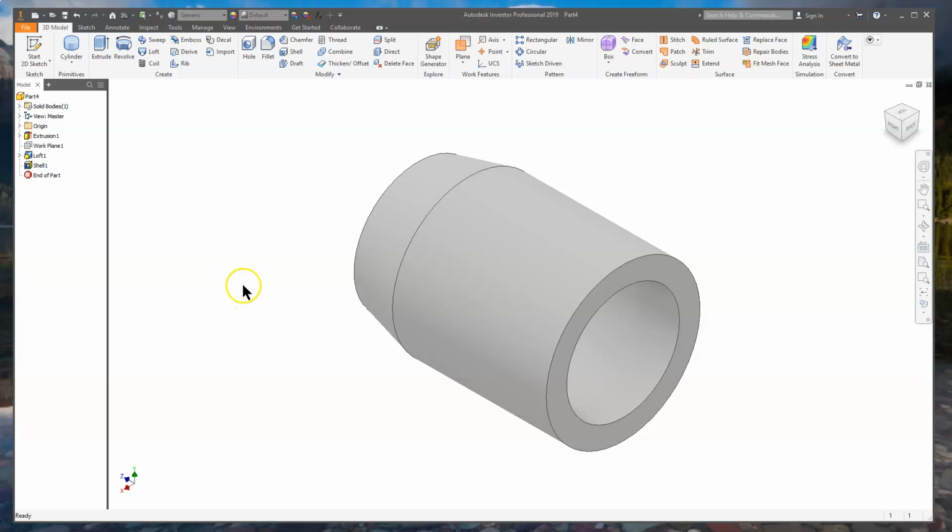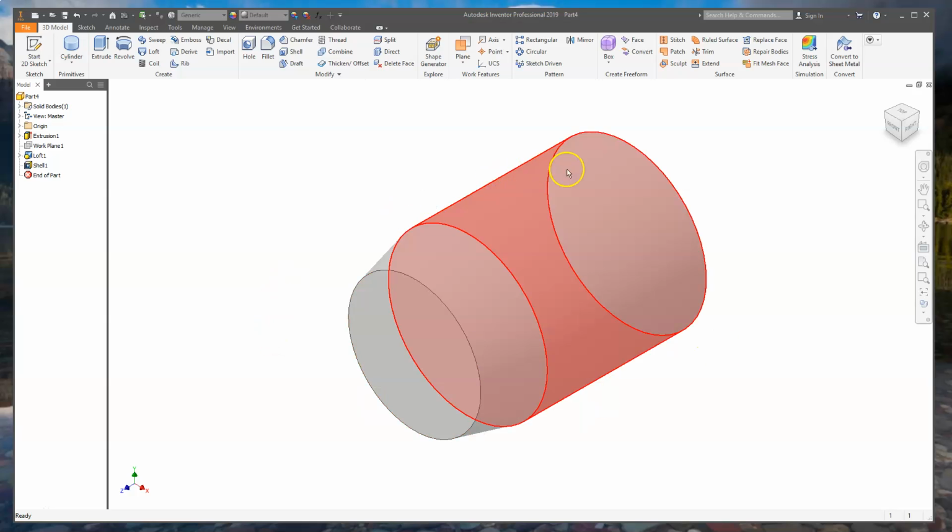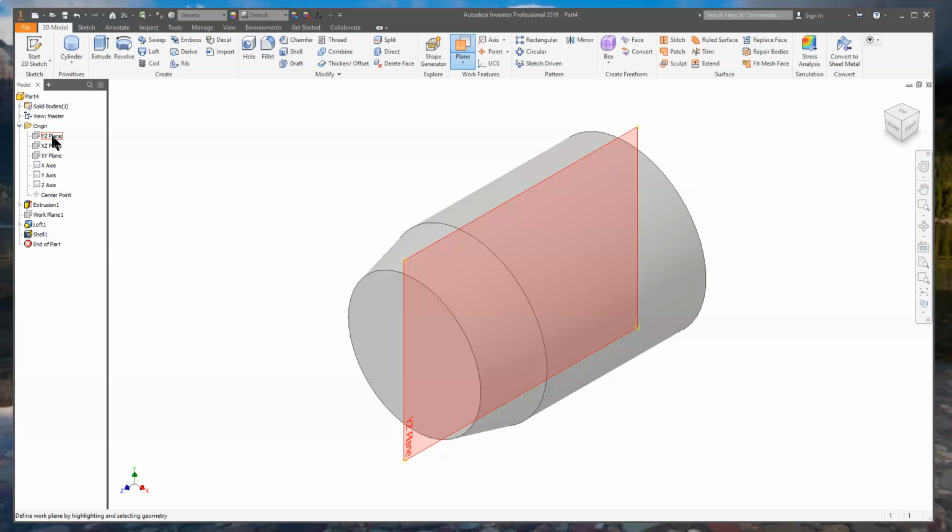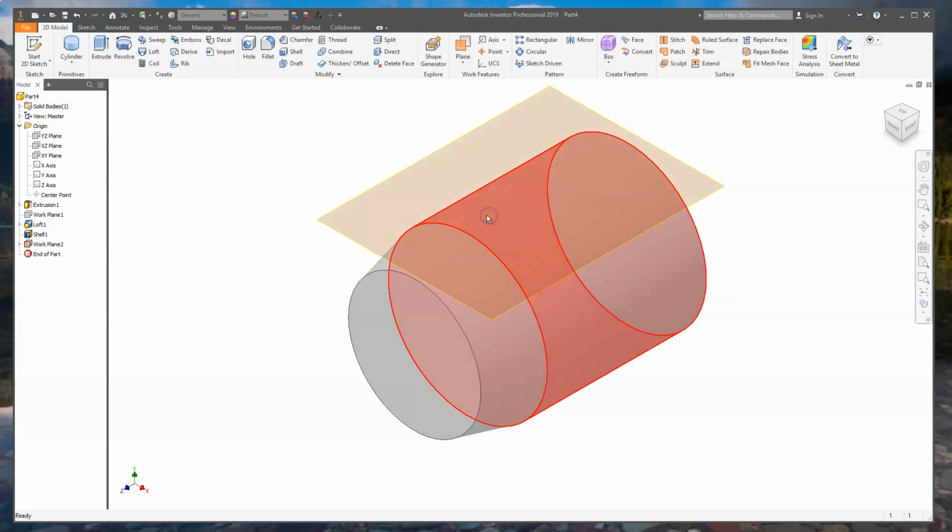Now what we're going to do is click on the home view. We're going to work on that plane on this surface. Now, do you remember? That was a couple videos ago. So on that, we're going to expand our origins. I'm going to click on the plane tool this time, and I'm going to say which plane do I want to do that on. I could do it there, could use this one. That one won't work. So I'm going to go on the XZ plane, and then I click there and then touch the surface of it. That way I'm working on the top.